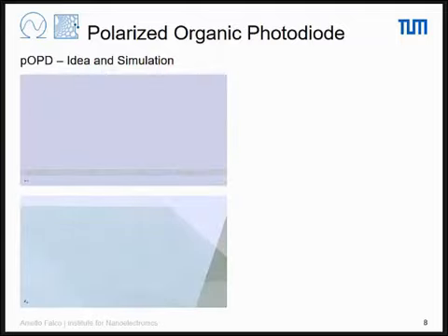The next stage is the creation of a polarized organic photodetector. So first, we need to create the polarizer. How do we do that? We use a material called ormostamp, which is imprintable, so it's a polymer. We just deposit a droplet of this polymer. We use a master stamp, which has some grid lines in it. Then we wait a bit and we expose it to UV light. The underneath polymer cross-links, so it becomes hard and replicates exactly the stamp that we used before.